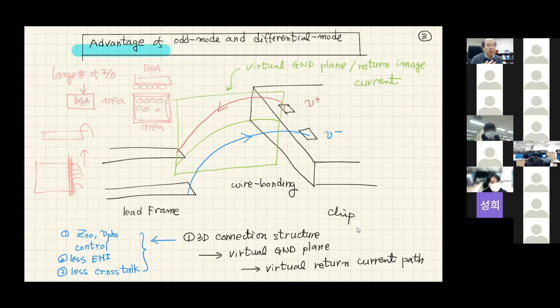Why do we have to increase the number of interconnections? Because we wanna increase the bandwidth between our device and other devices, like from GPU to DRAM. We wanna maximize data bandwidth to achieve high-speed machine learning calculations or metaverse calculations. We need very large and high bandwidth between GPU and memory. Another possible case is because of power.